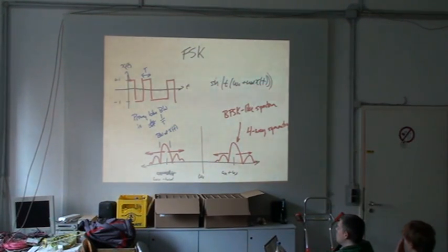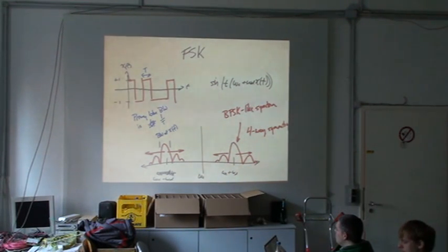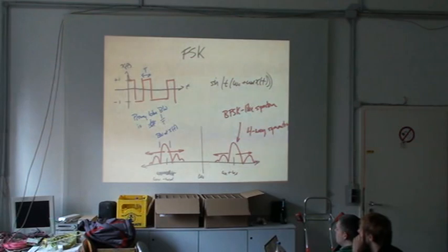If you look at this in the frequency domain, you see the same kind of spectral symmetry that you saw back in amplitude modulation, and that's because each of these carriers, the ωc at the bottom, is the center frequency. It's the average of the two frequencies that you're using. What you see at the bottom of the screen is just one side of the true spectrum. There's another copy of all this over on the negative side, so there's actually symmetry if you take the whole spectrum into account.